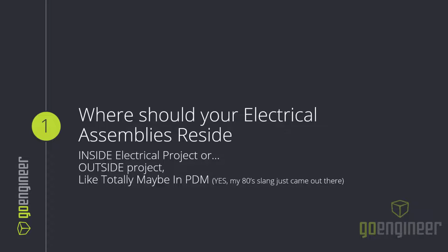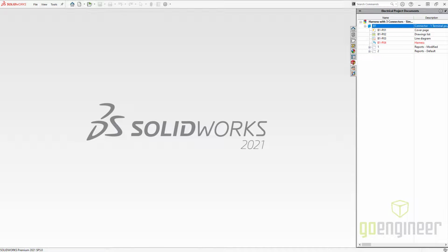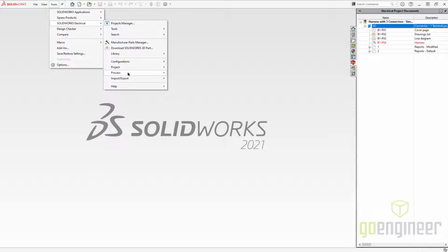So let's take a look at something here. I'm going into the Electrical 3D, again the tab on the right there. I'll go up to the Tools menu, SOLIDWORKS Electrical, down to Process, and over to SOLIDWORKS Assembly. If you went into the schematics program, the program I brought up earlier, on the Processes tab you can do the same operation. So it can be done in Electrical 3D, or also in schematics. Either place.